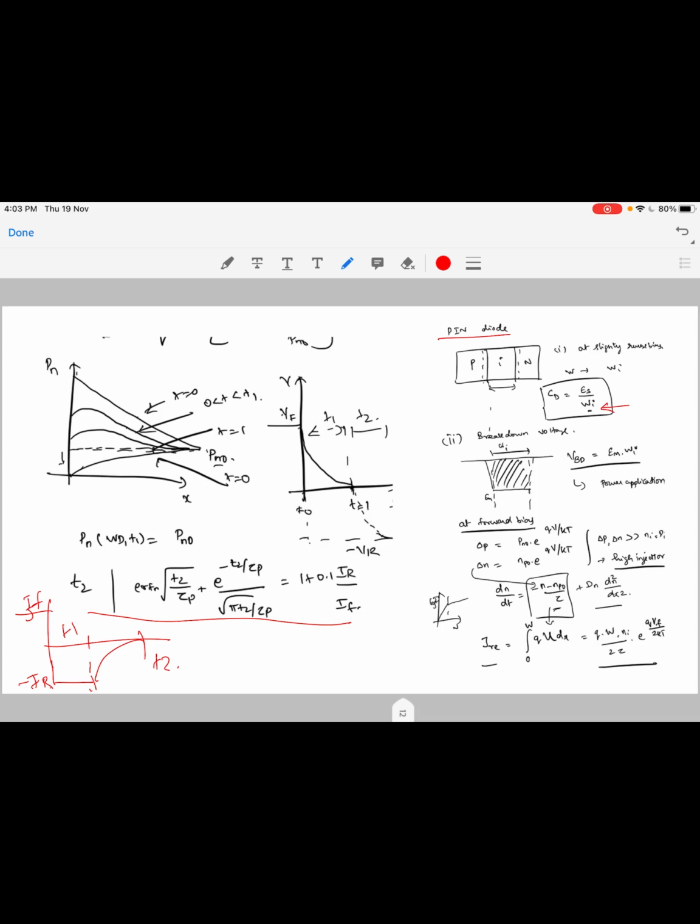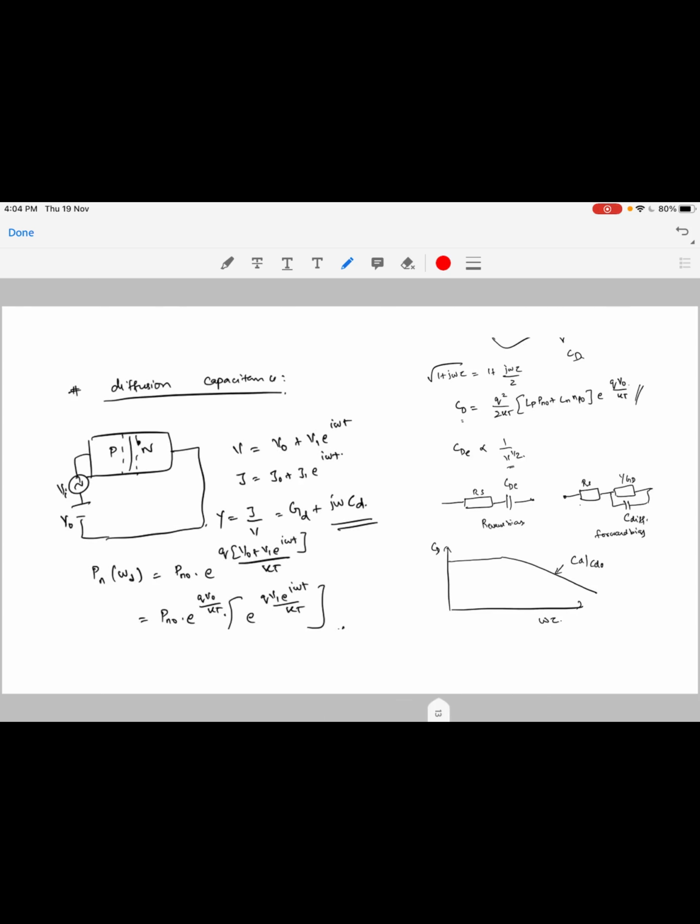So it will have almost a constant depletion capacitance, and it also has very interesting RF characteristics, as we saw during our detailed discussions on the PIN junction. It is used as a pure resistance in the RF domain and such. We also saw interesting characteristics of capacitance in forward bias.